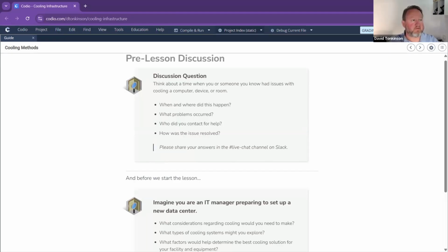Laptops overheated from Calvin. George says, had to repaste my HP laptop because it would overheat. By repaste, were you actually popping out the CPU? Or not quite popping out the CPU, but repasting as in using the thermal paste to recouple the cooling fan to it.